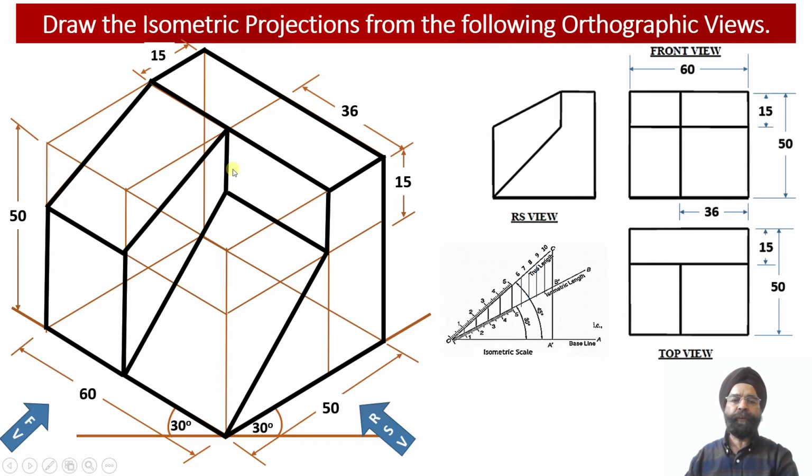So into the profile plane or the side view projections, this is also true shape of the inclined vertical web which is located onto the left hand side face of the solid over here. And this portion is also true shape into the elevation projection view because it corresponds to this surface which happens to be parallel to the vertical plane over here.